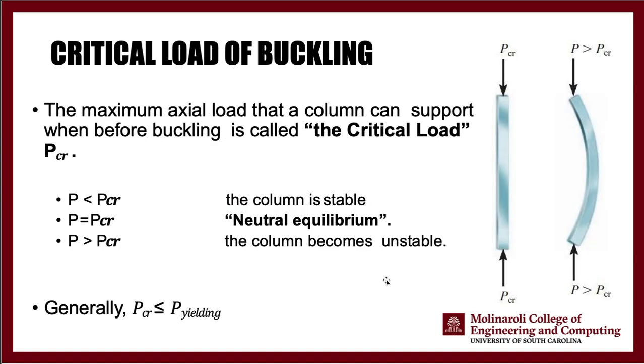The important part of buckling for us, though, is the critical load of buckling. The idea is if your load is smaller than the critical load of buckling, even if the deflection happens, your column is going to be stable, meaning that it will go back to its original location when the load is removed.